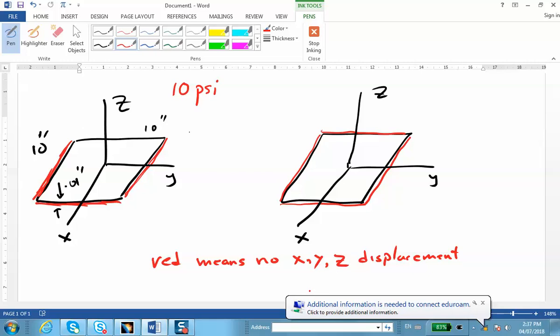Shell elements cover two-dimensional topologies such as instrument panels, let's say thin wall pressure vessel, hood of a car, and things like that. Now, they go on the surface. They don't have literally any thickness as we did in tetrahedral elements, solid elements. What I would like to do is some more problems.